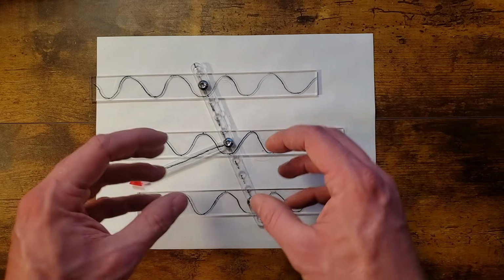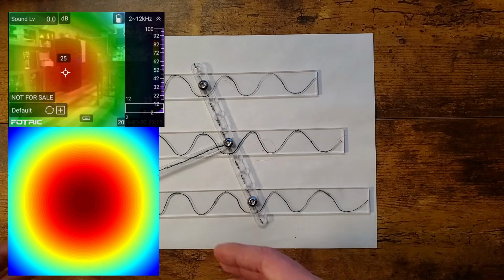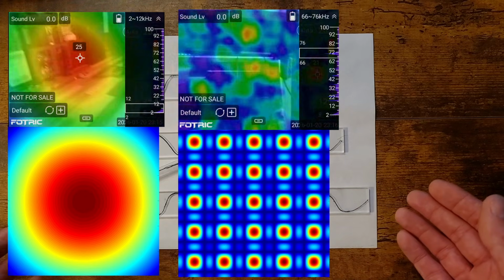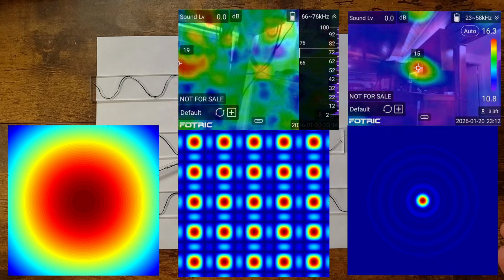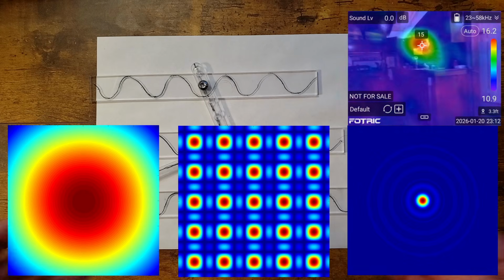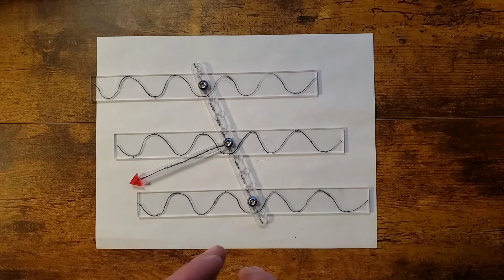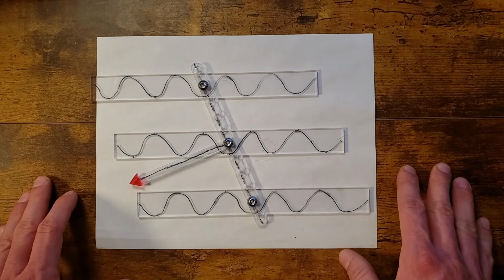A small array with a few microphones won't have artifacts, but will be blurry. A big array with few microphones won't be blurry, but will have tons of fake spots in the image. And a big array with lots of microphones is expensive and complex to make, and physically unwieldy, but will make a sharper picture with no artifacts. And once you go to a 2D array, the arrangement of these and trade-offs between arrangements gets significantly more complicated.